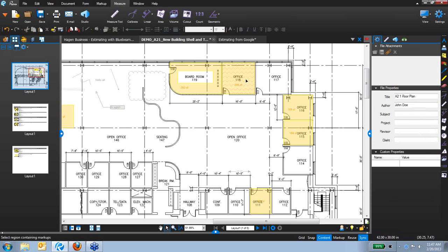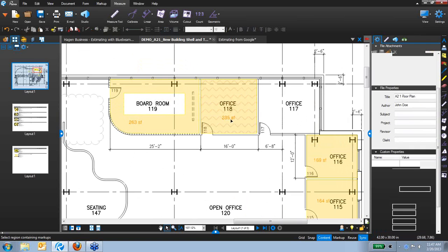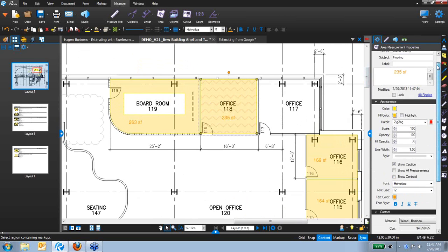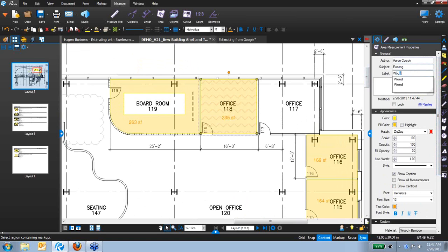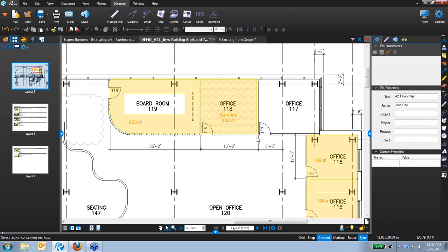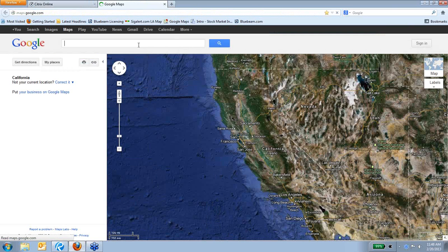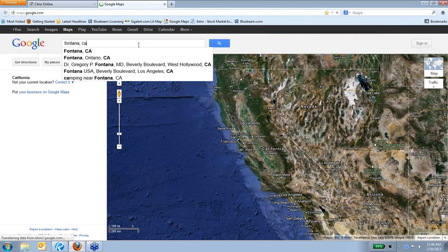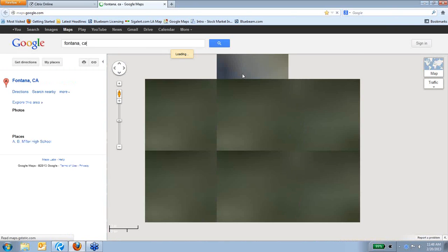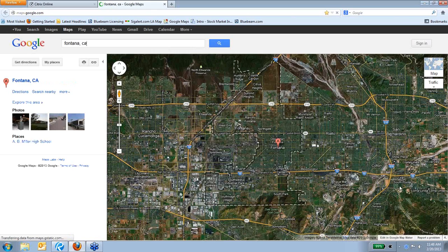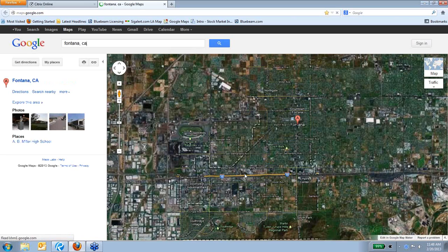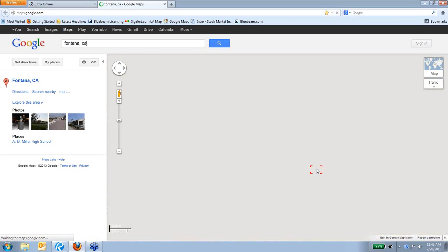And on the Google Maps, even when you're doing an aerial takeoff, from above, you really want to make sure that you have a photo that is directly above rather than at an angle, because you will get some things in Google Maps that are at an angle, and then everything kind of gets skewed, so your accuracy will not be as good. Yes, you definitely want to be careful in that. Even when I was grabbing the image a little earlier, I almost made that mistake where it had a 45-degree tilt, and then I had to force that off. So definitely be careful of that. You might want to make sure that's directly overhead. That's going to give you your best estimation.